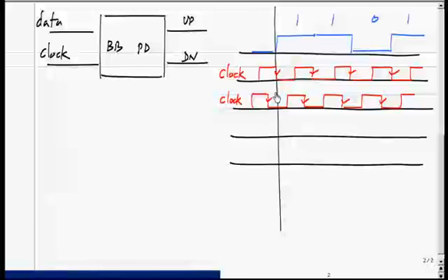That means that the control voltage should go down, so the phase detector should put out down pulses. So the up will be continuously 0 and the down pulses will be 1 for every time there is a data transition.